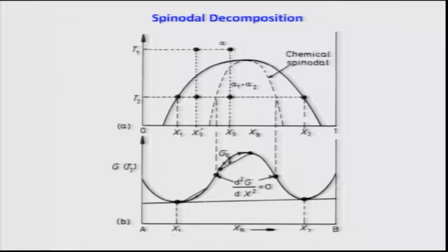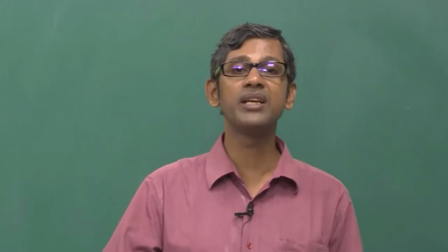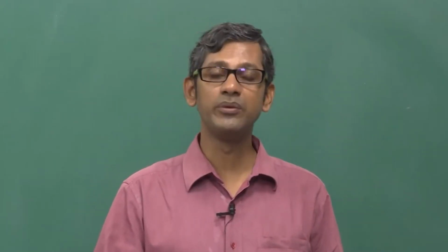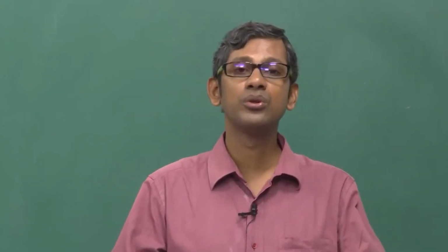Now if you have such a free energy curve, we can use these free energy composition diagrams to generate phase diagrams. We know that normally in the lectures we do it the other way, we just show you free energy composition diagrams when you know the phase diagram. But normally free energy composition diagrams obtained at different temperatures can be utilized to generate the phase diagram.